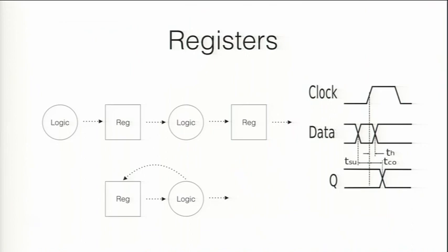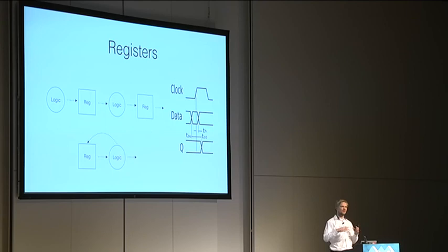With the lookup tables, you can, for example, make a very simple adder. You can have an input signal that is 4 bits, and you add a 1, and you get another output signal that is 4 bits as well. And the question is, how do you, for example, implement a counter? If you take the output of the adder and feed it directly back into the adder as input, then you have a combinatorial loop, and it will do nothing useful. To avoid that, because we want to do something useful with FPGAs, there are so-called registers. Registers are like data storage.